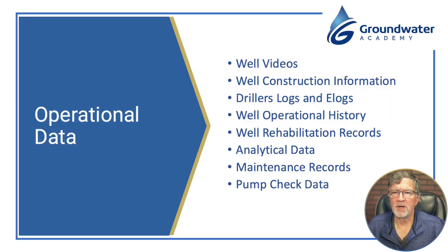All right, operational data. This is the fourth area we want to look at. That's going to be kind of a hodgepodge of things. Well videos, obviously very important. We recommend every time you pull the pump, you do a well video. Well construction information, driller's logs, e-logs, well operational history, well rehabilitation records, analytical data, maintenance records, pump check data.